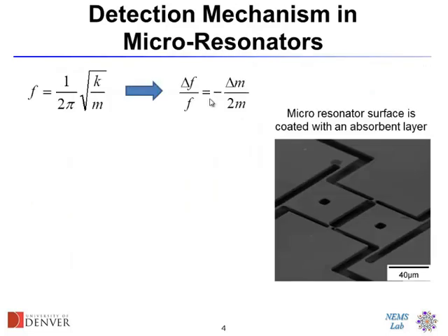Well, I believe there's different techniques, but I've been working on resonators over the past more than 10 years. So that's pretty much the only thing I can do. Any problem I see, I try to solve it somehow with a resonator. How do we make a CO2 sensor using a resonator? The concept is pretty simple. If you can somehow absorb the CO2 onto the sensor, the added mass could change the resonance frequency.